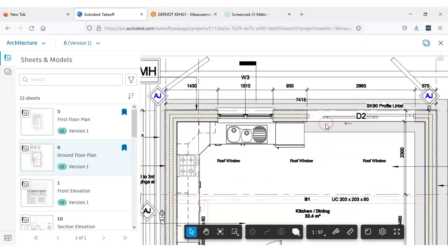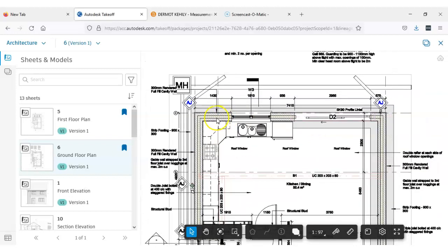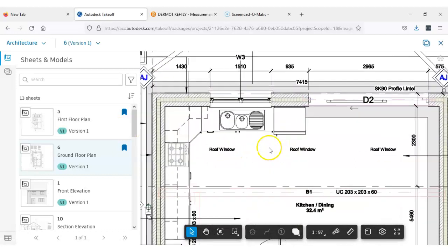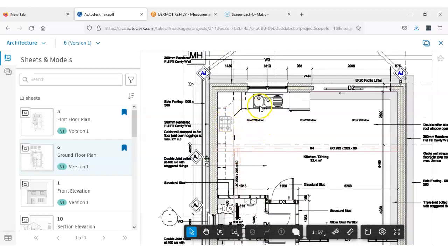Now, you might think that it should be 1:100. That's the way it should have exported out, but it doesn't always work out that way. So you calibrate first. You would know if it was 1:100 if your calibration came up at 1:99.9 something. Then it's just how you clicked. But I'm a little bit off, so I can imagine that it just wasn't exported as a 1:100 drawing. So I'm calibrating it now, and I should be happy enough with that. Okay, so let me do a quick measurement on this, and we can get started just to give you an idea of what you need to do.